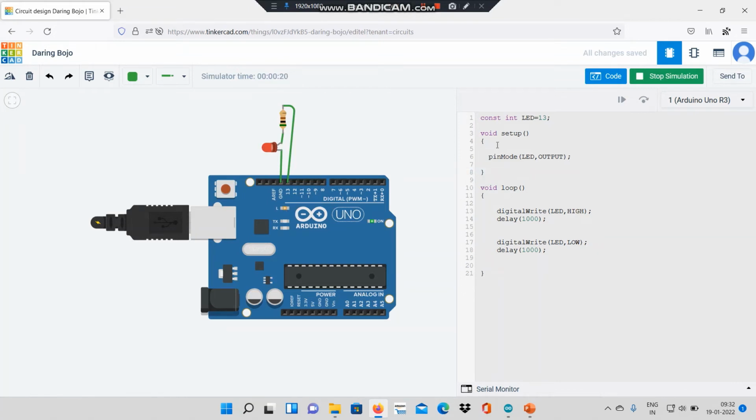Okay. So in this video, we have learned how to use variable names instead of pin numbers directly. So instead of using a pin number every time in the program, what I can do is I can use variable names instead of pin numbers. It becomes very easy to write the program and remember it in the code because this variable is given the name LED itself. To improvise this code further, I can give this LED name as LED R signifying red LED.